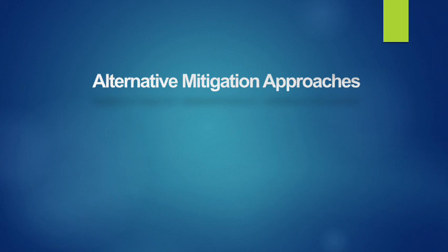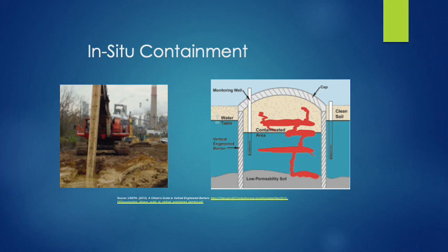The previous examples focus on approaches that break down or remove contaminant mass. In some instances, it may be more appropriate or more cost-effective, or both, to allow the contaminant mass to remain within the subsurface, provided protective conditions are introduced. In some cases, it may be appropriate to allow contaminated soil, contaminated groundwater, or both to remain at a site, provided that a protective containment structure is installed.